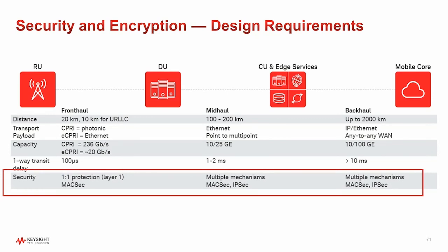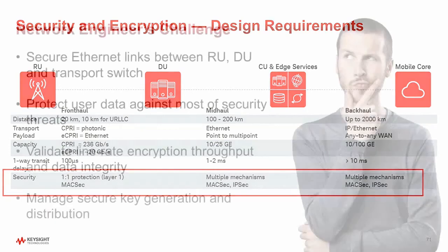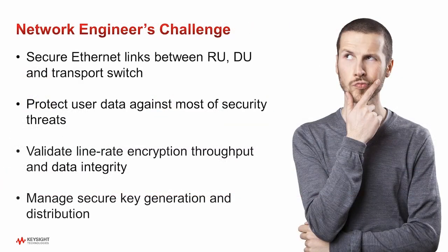According to the eCPRI specification, vendors may optionally implement different encryption technologies like MACsec or IPsec. However, these encryptions impose additional processing overhead on the network elements. The switch vendors need to optimize the implementations of the security protocols so that the latency requirements of the 5G NR radio are met. Which technology to be used for encryption is an open subject right now, and it's being debated in forums like the O-RAN Alliance and others.